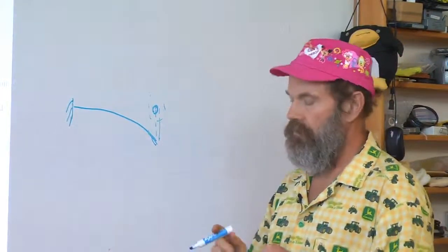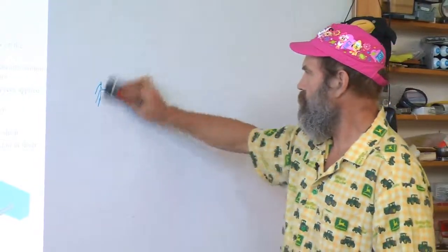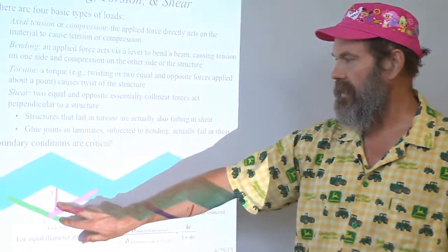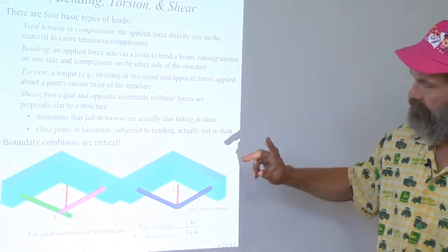The lesson here, on this level of detail, is that you start thinking about manufacturing and whether you use discrete elements or elements that are formed and then attached. It may seem simpler sometimes to use two simple parts and connect them as opposed to one part that I had to bend.